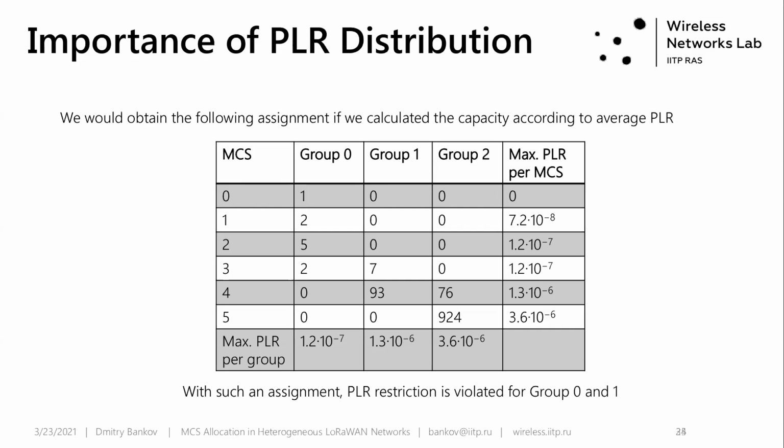Andrei Belagayev asked whether the Q value depends on the selected MCS of the packets in collision. Well, I think it might depend on the selected MCS. It's just some value, the 3 decibel value is given in the datasheet of LoRa devices, and in the datasheet it says 3 decibel for all MCSs, for all spreading factors.